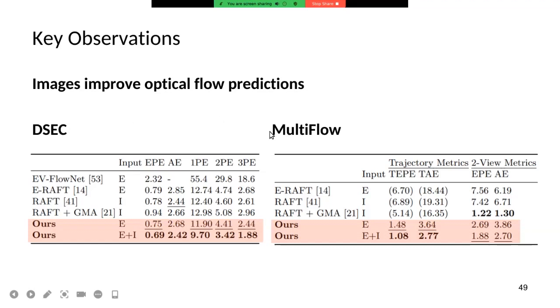And you may ask yourself, okay, but I thought maybe optical flow is like great for event cameras. Do we really need frames? And the point is that event cameras, they have this threshold that I mentioned in the beginning, this contrast sensitivity threshold. And what this does is it basically quantizes the contrast. And this quantization of the contrast makes you lose a little bit of detail in the scene. And these details are sometimes important, for example, to match the trajectory from the reference time to your target time. This is where the frames can really help.